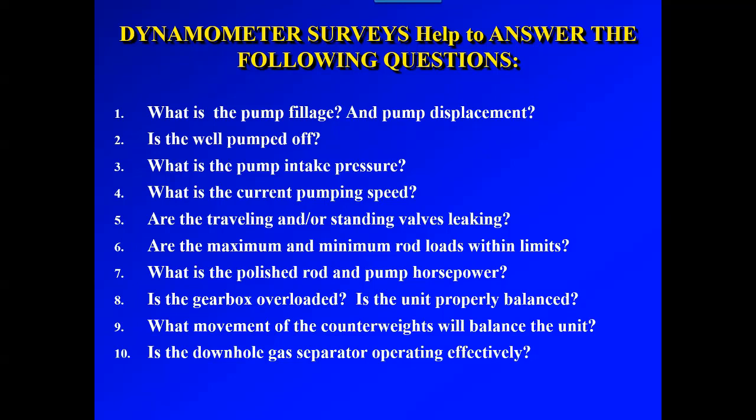Is the well pumped off? You can also calculate your pump intake pressure, determine your pumping speed based on the accelerometer that's in the sensor, as well as conduct traveling valve and standing valve tests. In the fundamentals section of this course, we're going to talk about testing traveling valves and standing valves, understanding what the valve tests look like, how to interpret them, as well as identifying basic card shapes for worn traveling valves and worn standing valves.